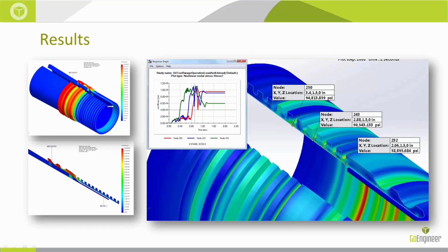So why would that happen? Well, we're looking at 3 different points along our tube here, and you can see that really steep section is where the product buckles. So we've by no means yielded the material, but as it's changing shape, it became significantly weaker and just popped out. This is one of the phenomena, right? It's called buckling, and we're able to see it in a nonlinear analysis.